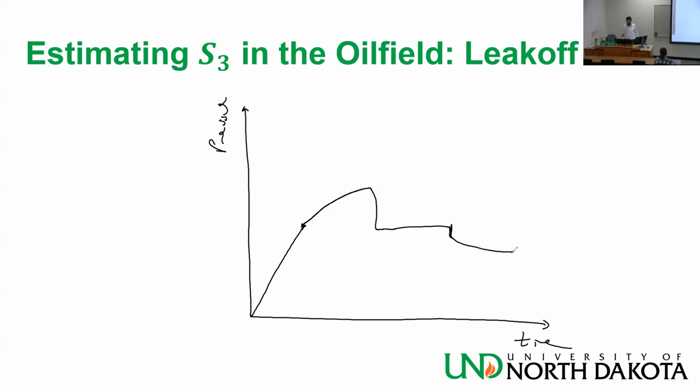But in leak-off testing, we don't go all the way to failure. This is the leak-off pressure. This is the breakdown pressure. And I told you, all the way here, I will draw it green, I can have fracture initiation at any point. Here. Any point. I can have fracture initiation at any point.